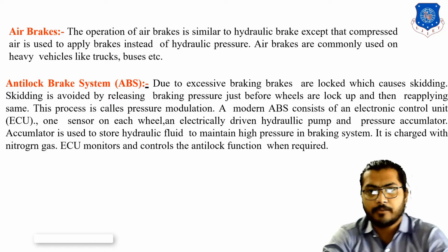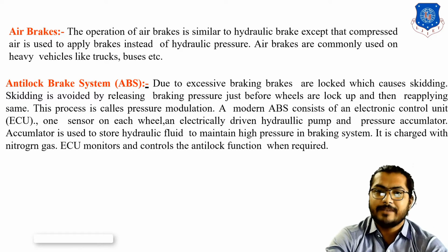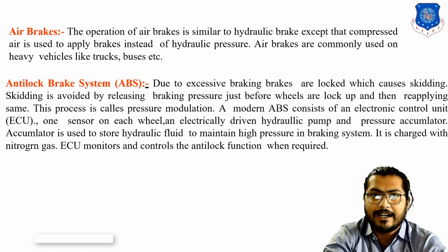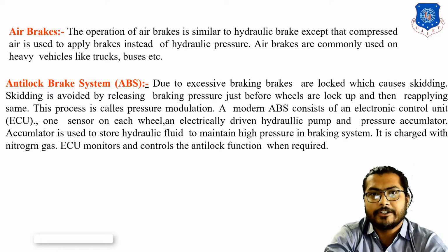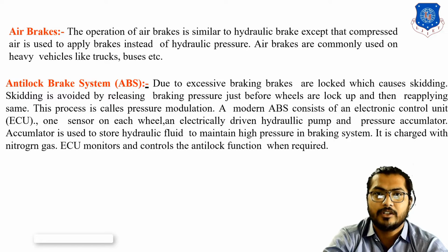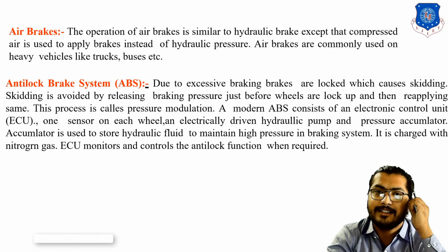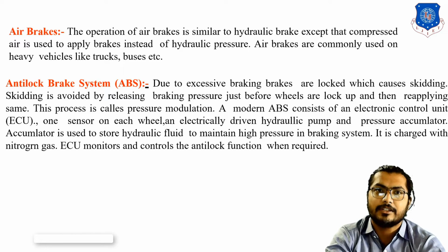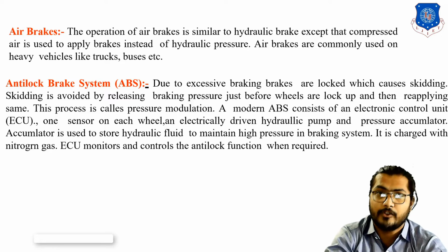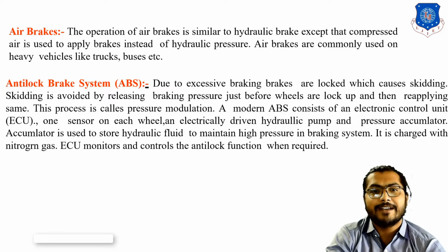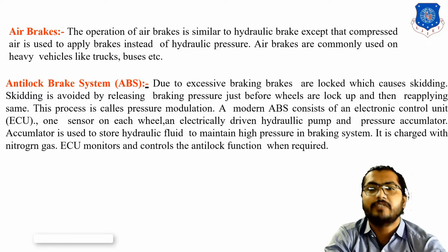What is the difference from the other brakes? Okay, due to excessive braking, your wheels are locked, which causes skidding. If your wheels are locked and power is supplied continuously, at that time the wheel of the vehicle will skid, or your tire will be skidding, or we can say slipping. Okay, and in that condition it is injurious for the drivers or passengers. If you do not have an anti-lock braking system, it may be a very dangerous phenomenon, or it may lead to an accident. Okay, skidding is avoided by releasing the braking pressure just before the wheels are locked up.